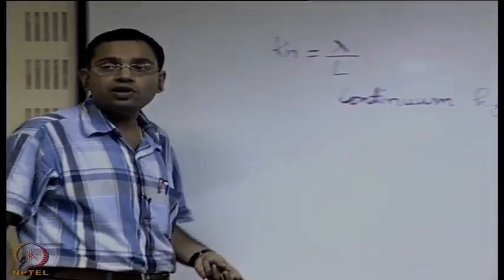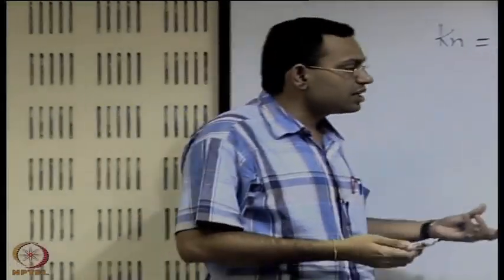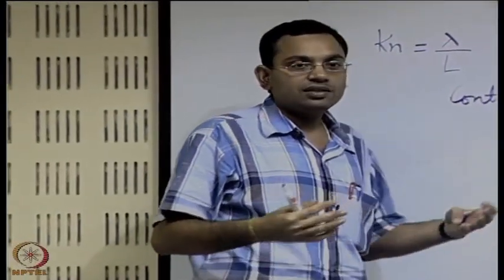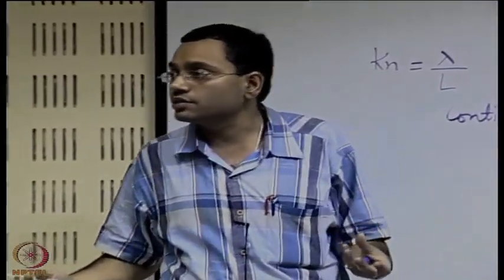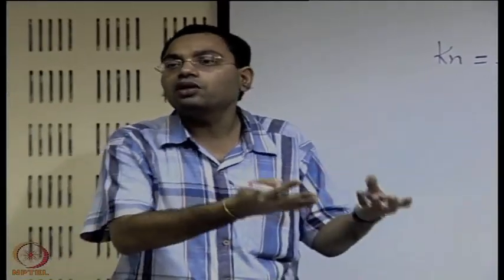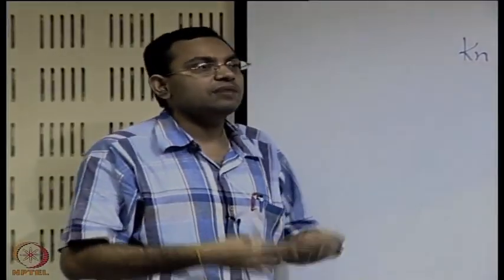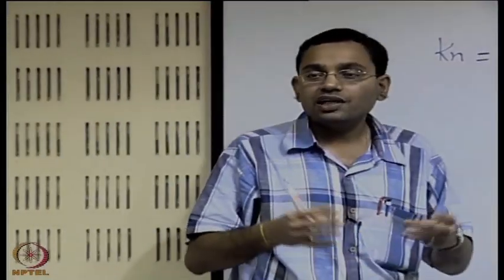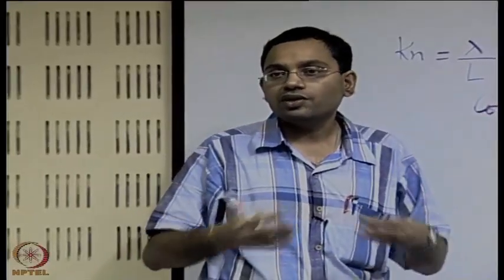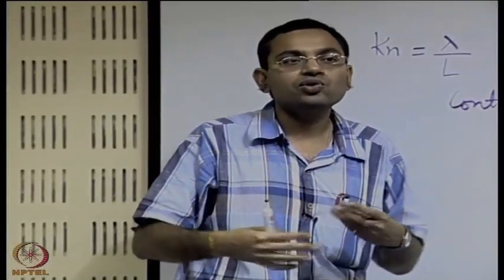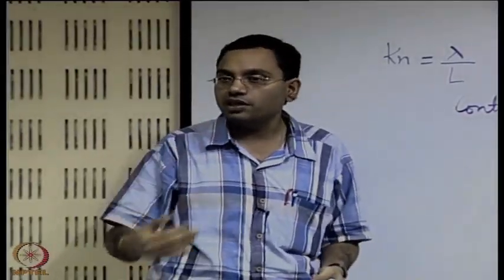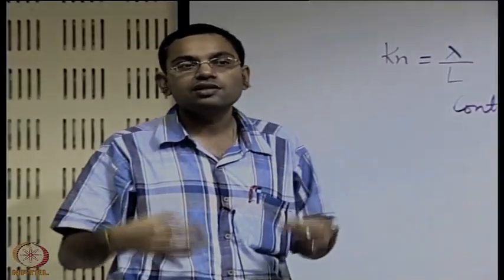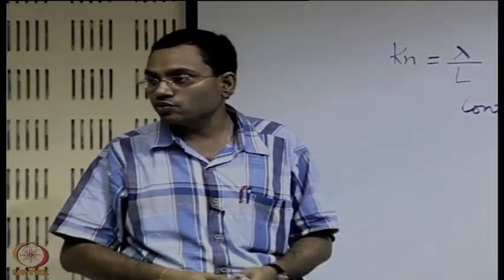So, what is the continuum hypothesis? It tells that we treat the fluid medium as continuous matter, disregarding the discontinuities in the system. There are discontinuities if you look at the molecular level, there are molecules, there are gaps and so on, but if those are sufficiently compact, then you may treat it as continuous matter. Once you can do that, you may use the well known rules of differential calculus to talk about the changes in properties from one point to the other. So, you can talk about simple gradients, second order derivatives and so on.